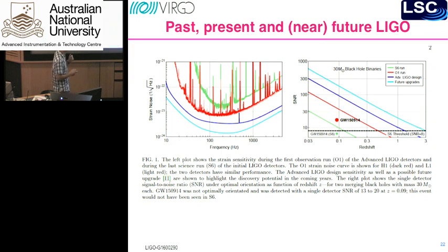Some people plot the energy spectral density of the signal on these power spectral density plots, and it sweeps across like this and then comes down at about 200 hertz. But I don't like that at all, because they're two completely different things that don't have the same units, and people are trying to plot them on the same axes, which is silly, I think.